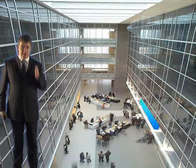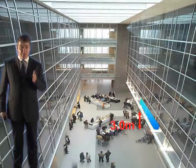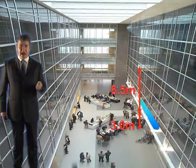The height of rise is the distance from the lowest spill edge to the base of the smoke layer. That is from 3 metres above ground to 9.5 metres above ground. In this case, it's 6.5 metres. So that's the height of the rise of the smoke from the spill edge. Therefore, in this case, the most appropriate model to use is the guidance in PD 7974 Part 2 to calculate the mass flow rate. So that's the one model we're going to use with this spill rise.